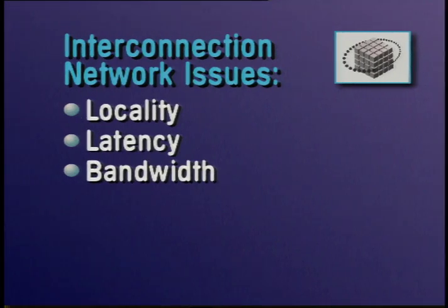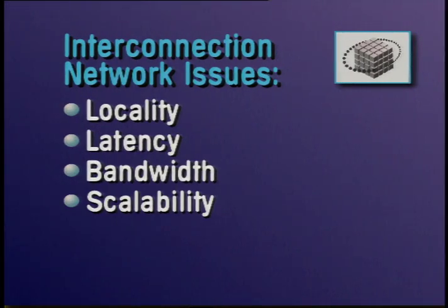Microprocessor shell and network switch logic are clocked by a single synchronous 150 MHz clock distribution network. Market requirements for massively parallel systems dictate support for a wide range of system sizes with incremental pricing structures. The network must be scalable with a fairly linear increase in cost to match linear increases in the number of processors.